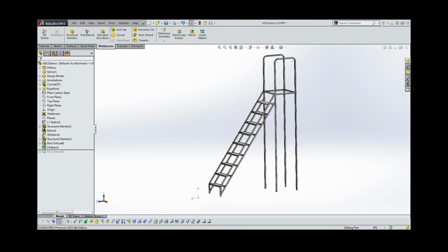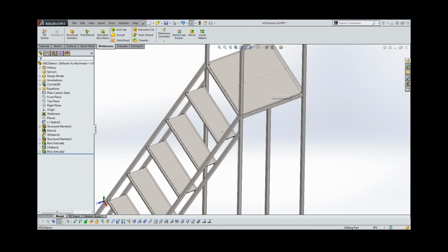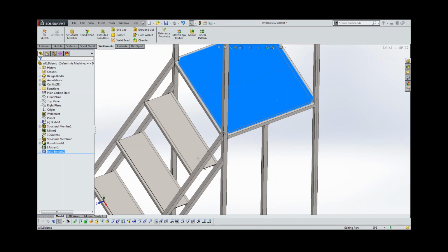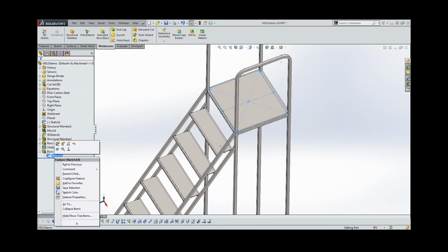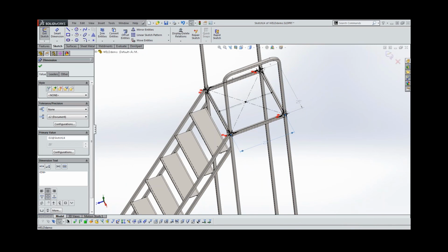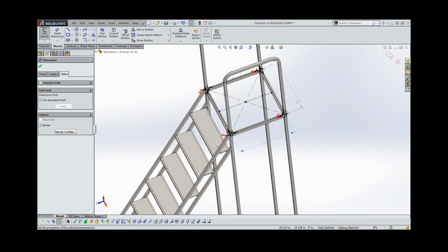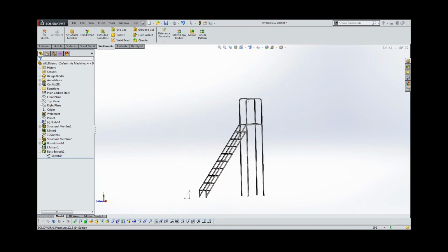And then finally, we're going to roll down. Let's put a little deck on it, and we've got our deck. Again, if we click on this sketch, you'll see our dimensions here grayed out because they're driven. I've just linked it to existing geometry, so I don't have to do anything with them. They just stay driven all the time. So something you really want to look at there.